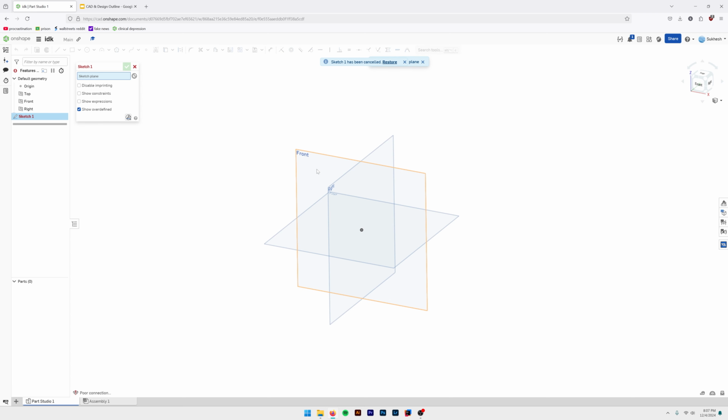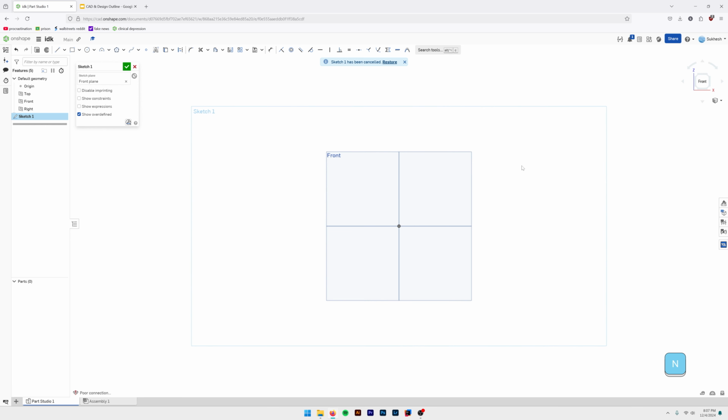So if I create my sketch here again, press N, now it centers to the sketch because it knows what it's centering to. And if you press N again as a bonus, it flips to the other side. Notice how the sketch is now reversed. You switch to the other side. I haven't really found a use for it, but cool party trick, I guess.